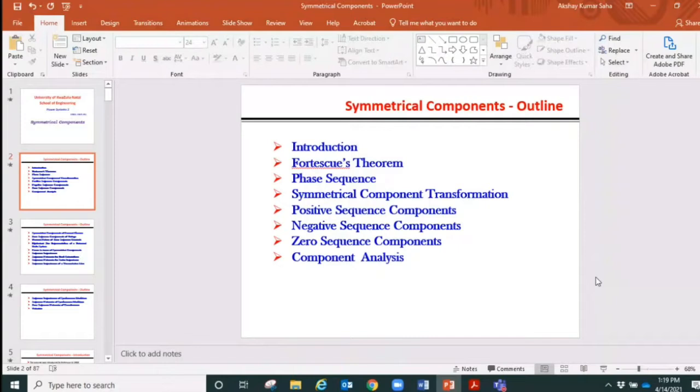If we assume that our generator is ideally constructed, then we will get three-phase voltages out of the generator terminals that are balanced, meaning all the magnitudes of those three-phase voltages will be the same, and the three phasors of those three phases will be separated from each other by 120 degrees. So magnitudes are the same, the phases are separated by 120 degrees, and then they have a direction of rotation that we will see on the diagram.